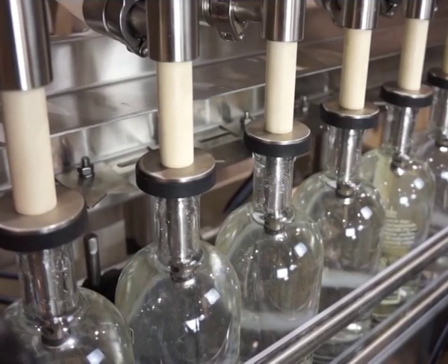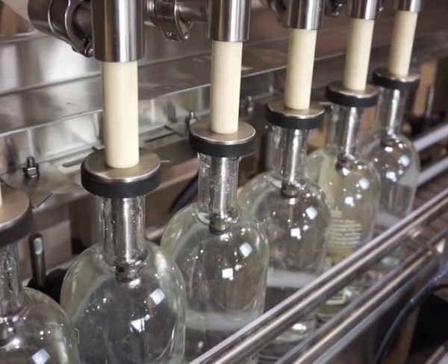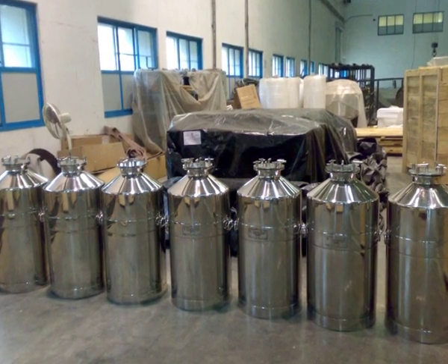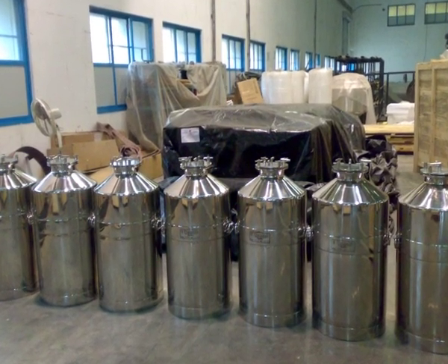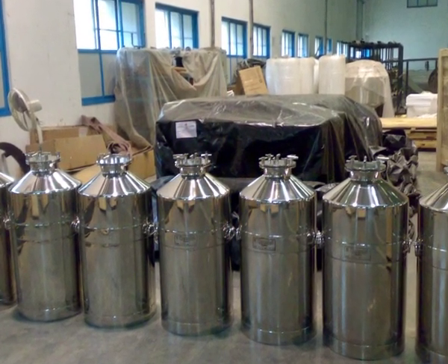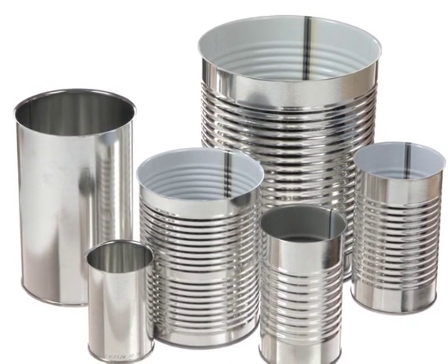Pressure filling equipment is more expensive than cold filling equipment, but the running costs are lower. With all these processes, removal of the head space air by vacuum or purging with propellant vapor is essential, as otherwise the internal pressure would be lowered. After filling and closing, the containers are tested in a water bath at 55 degrees Celsius or above to check for leakage. The containers are then dried and the buttons applied.